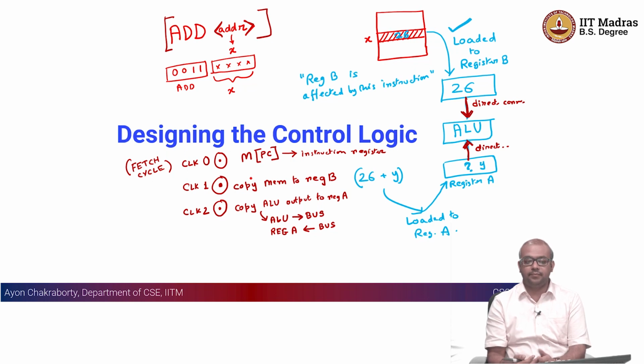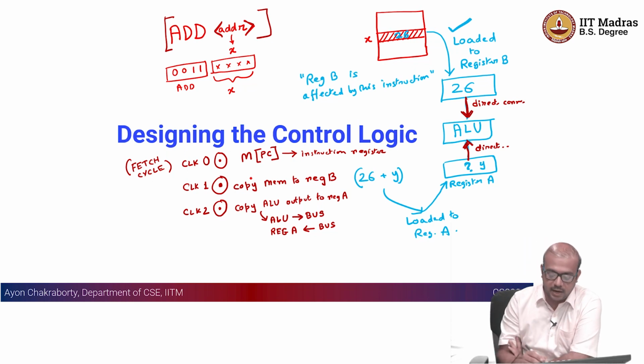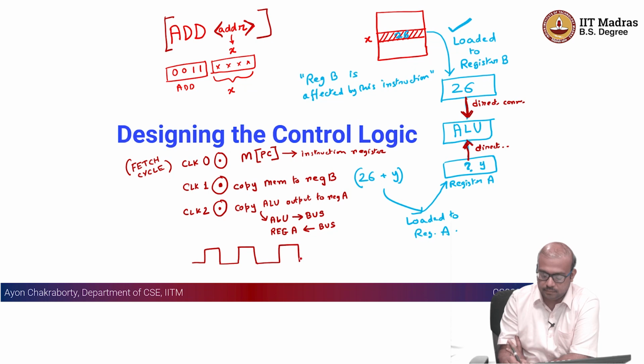After you finish these clock cycles, you actually get the instruction executed, and this is what is known as an instruction cycle. Okay. So, if you look into how an instruction is executed, you may have multiple such clock cycles, right. In this case you have 1, 2, 3, 4 and let us say 5.